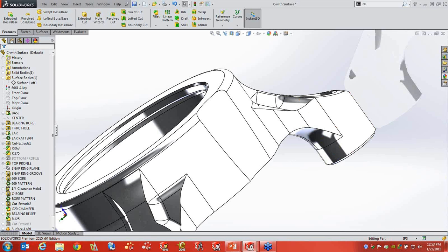Now, I do have a few questions listed here. One looks to be related to Freeform. Can you add the curves or point at a specific dimension? No, you cannot add the curves or point at a specific dimension. If you know exactly where you need that, most likely what I would do is just put a point at that location, and you can move your curve, and looking relative to it, you can just about pick exactly on it. But you can't give an exact dimension to the curves. That was something that was asked real early on, and they never really added that to the software.